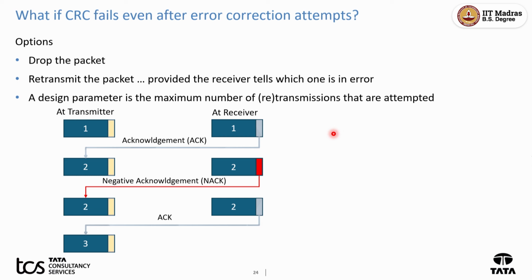But this is also inefficient. Why? Any guesses? Why is this inefficient? Good question, very good question. Someone asked this question long ago, so I'll answer it from the point of view of wireless channels. I told you about that repetition coding. So the repetition coding is used for those bits. These are heavily coded, just one bit, sometimes 2 bits, 3 bits, depending on when we get to MIMO and all, but they are heavily coded. So it is very, very unlikely that you'll lose this.